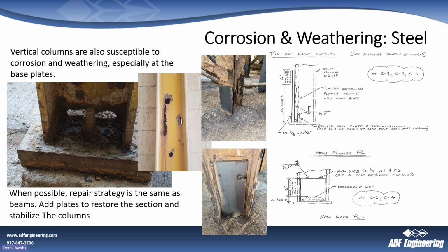Okay. But we'll add plates. We're trying to restore that section of the loss that we've lost due to corrosion, right? So if we're losing pieces of the web here, we're going to put a plate in there, and we're going to repair that and restore that. So typically that is the goal.